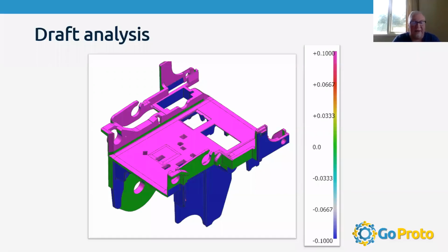So again, points of discussion. We'll ask for draft to make the tool run optimally. But again, it's got to fit your design. If you add draft to the walls, it's going to change the dimensions just a little bit, so we want to be respectful of that for your design.